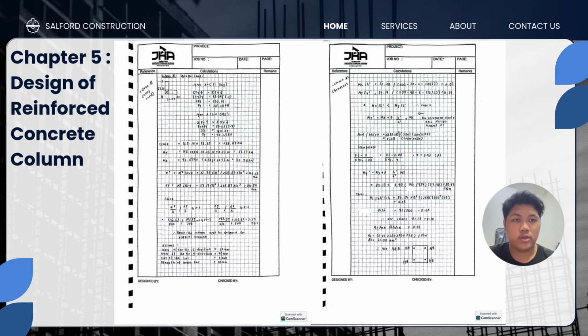Then using formula from structural design codes or Eurocode, the following parameters are calculated. The first one is effective depth and overall dimension of the column, the second one is interaction ratio between axial load and bending moment, the third one is required reinforcement area for the given load condition, and the last one is check for the neutral axis position to determine the stress block.